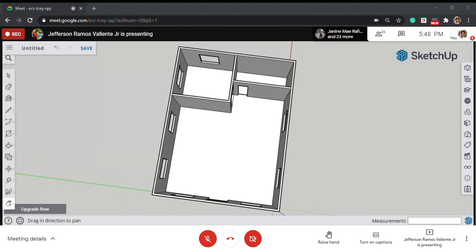So in the building code, the minimum dimension of any room should not be less than 2 meters. And the minimum area of that room should not be less than 6 square meters. So look at your rooms, they're small. They actually don't pass the building code. So if something happens, like a fire, it won't pass, and you may get penalized by the LGU. But we will discuss that further. I just gave the minimum requirements now in case you use them for your as-built plan.